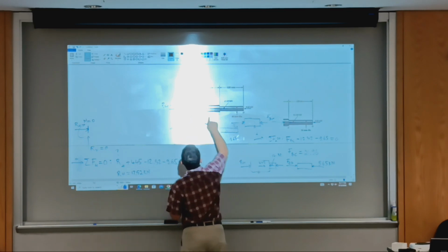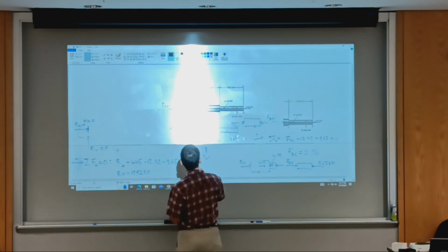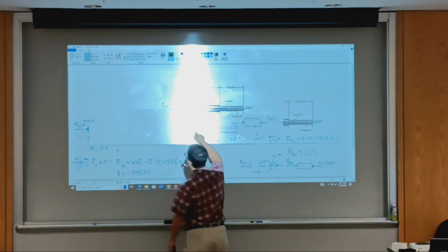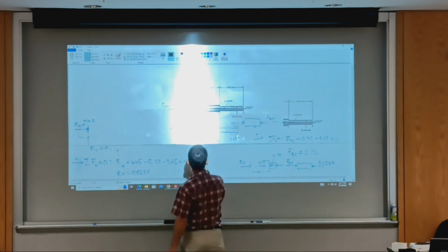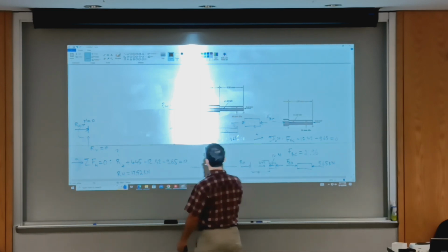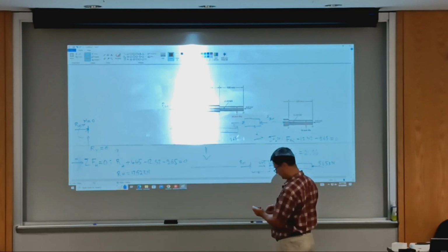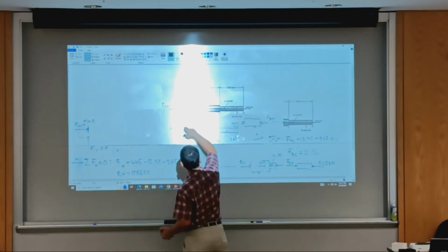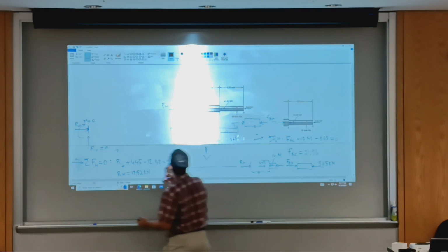It's just a matter of dividing these forces by the corresponding diameter. So the stress diagram is just going to be the load diagram divided, here and here, by the same amount, 25 squared times pi over 4. And I'm showing compressive stresses as negative. So I'm looking at 17.52 over 25. And by the way, we have kilonewtons, so let's go in shorter steps.